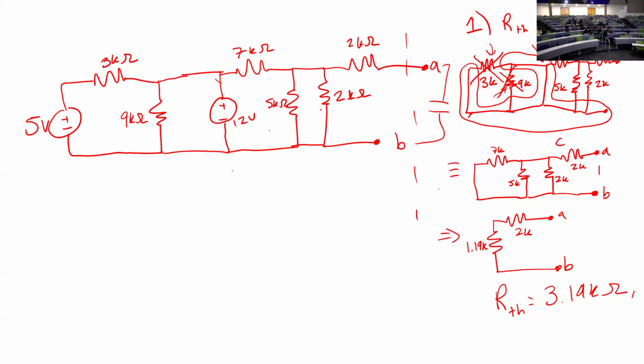Not necessarily. And there's no right way to do it either. It is purely what you see and what's easiest to combine. Because we're not going to end up back solving for node voltages or mesh currents here. So all that matters is, hey, I see 2 resistors in series, let me combine them. Or hey, I see 3 resistors in parallel, let me combine them. In what order you do that, just combine, redraw, combine, redraw, until you're eventually left with something like we have in the bottom right here, which very clearly just becomes 1 resistor because they're in series, okay? So it's whatever order, just keep simplifying with just your 2 rules of combining series and combining parallel. There will not be a case where you'll have to solve anything that doesn't follow the rules of series and parallel.